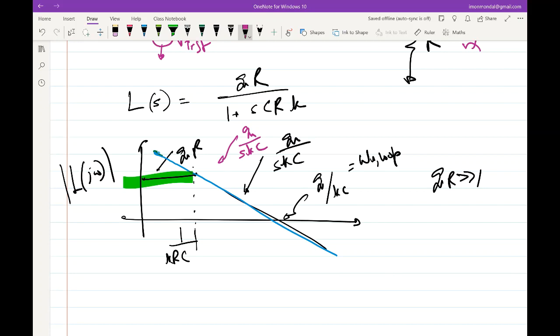What is constant? In loop gain, okay, so you mean till 1 over KRC in this case here. But if you have an ideal integrator, it is never constant, right? So 1 over KRC is at 0 frequency, then, right? R is infinity. So when does a negative feedback loop work as you want it to?